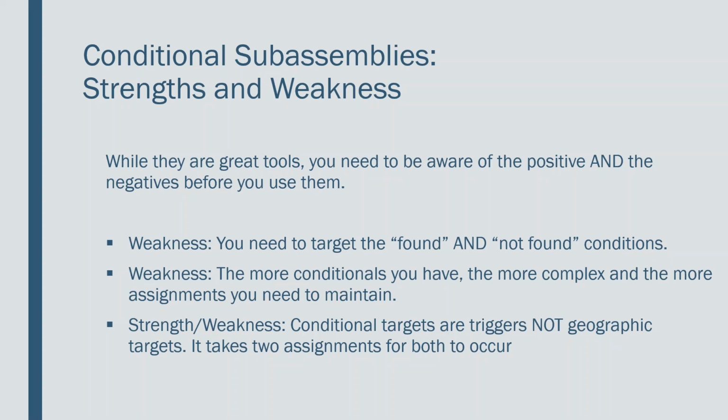So conditional subassemblies are not always the answer in every situation, but in a lot of situations you should at least investigate them and take a second or two to think through: will this work nicely here, or is it something that I should just make another region for? I get a lot of quizzical stares when people who know I love conditional subassemblies ask for help on something like that, and I say, you know what, it might be something you just do another region for. And they say, well, the conditional subassembly will do it. Yeah, but you're actually spending more time doing that than you would with the new regions. So keep that in mind.